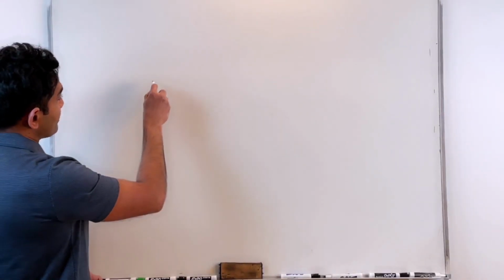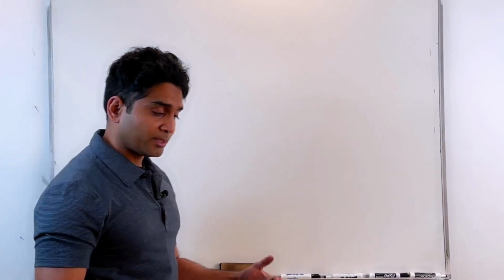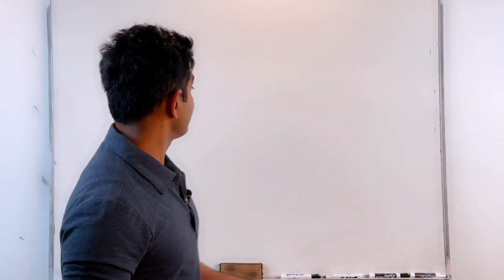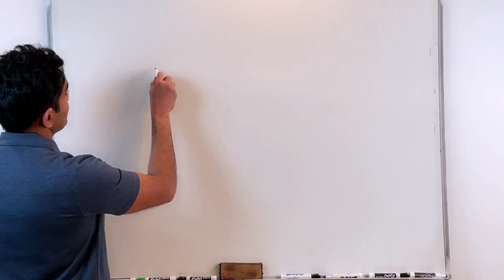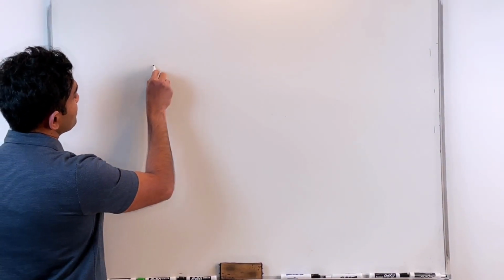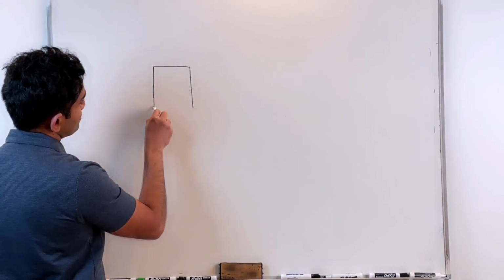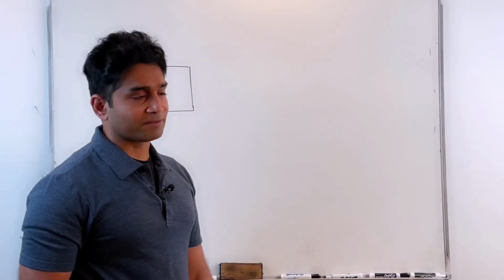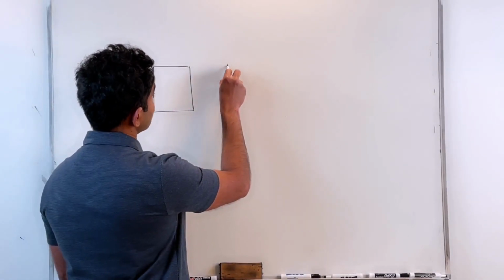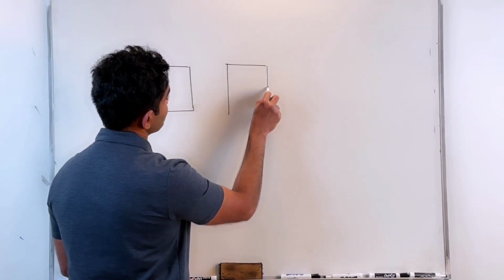Because that's a register, I have to use a D flip-flop in the design. In this particular example, let's design a 4-bit universal shift register. So I'll use 4 of these that can store 4 bits of information.